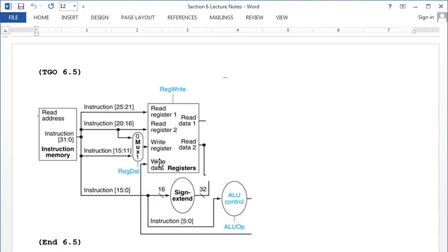So if you recall from the previous lecture, we had that 32-bit write input, and specifically, it would read the data out on the positive edge, and we had the program counter at the negative edge. The reason why we did it at the negative edge is so that while we're getting this address here, we can update the previous instruction immediately. So then we hit the positive edge, then we write out. That's how we physically obtain this write then read capability in MIPS. And that's why it's important. So you get that information back so you can have the most recently used copy of the variable to perform the correct operation.